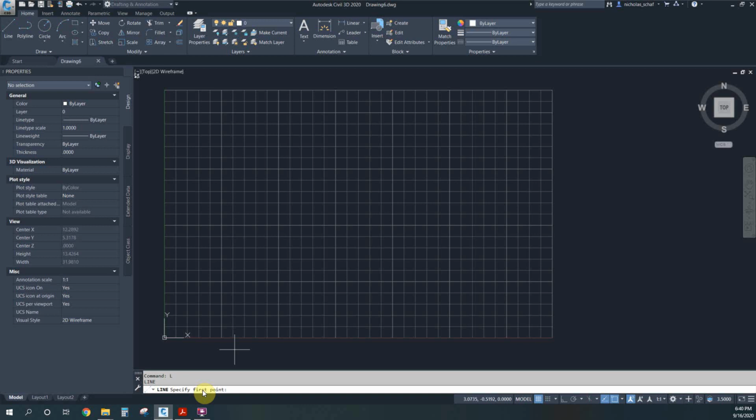Sometimes it asks for numerical responses. So for example, if you're inputting a circle, it's going to ask for the radius and it's going to look for a number. In this case, it's going to look for a button click wherever I want of the left mouse key. AutoCAD automatically assumes all numbers are positive unless you put a hyphen before it for the minus sign. And do not put any spaces when you're doing input because the space bar is equal to enter.